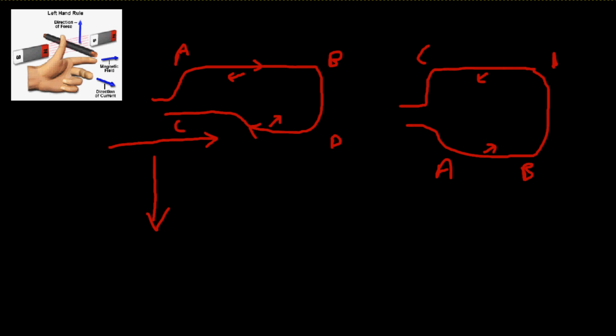And again, there are certain ways of increasing the speed of how fast this rotates. The first is quite obvious. You increase the current. If you increase I, automatically the speed of the rotation will increase. Also, if you increase the number of coils, the number of turns in the coil. Now here, just for simplicity, we're taking just one coil. If you look at the animation, it's just one coil.